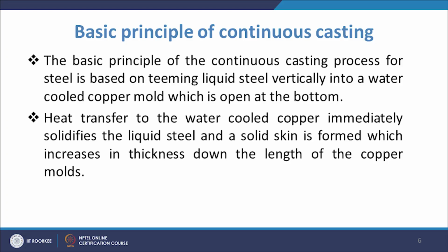That is why in this course we are going to discuss the role of the tundish, and how the tundish flow, or the phenomena which occur inside the tundish, are important as far as clean steel making is concerned. The basic principle of continuous casting is based on teeming liquid steel vertically into a water cooled copper mold, which is open at the bottom.